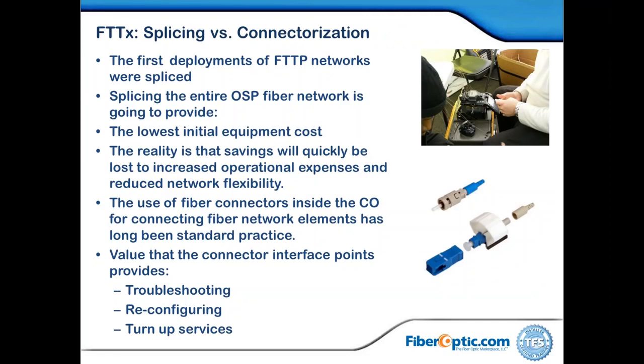Originally, these inexpensive, what we call cladding alignment splicers or fixed V-grooves, were said to have been a result of the nationwide FiOS projects, where we wanted stripped-down, cheap tools or splicing machines that subcontractors could afford to buy, and we could conventionally splice the system. So think of that as one of the original goals.